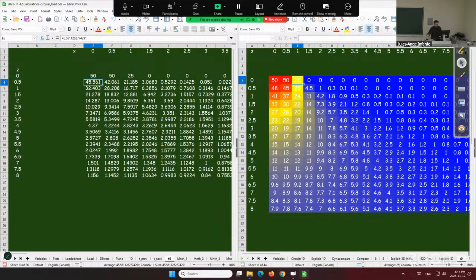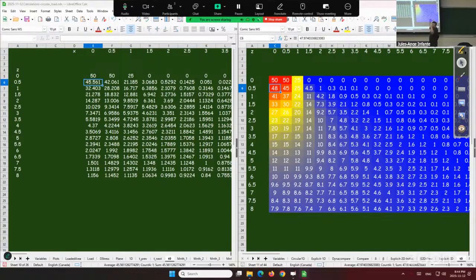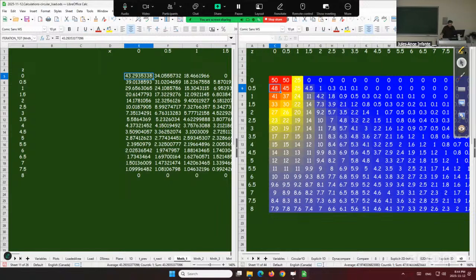But if we look a little bit below, already under the circular load, we don't get as big an initial pressure as we get with strip footing. Because in strip footing, we have an infinitely long loading in the direction perpendicular, while the circular load is finite. So that shows in the 1 month, it should show also, it should decrease faster.